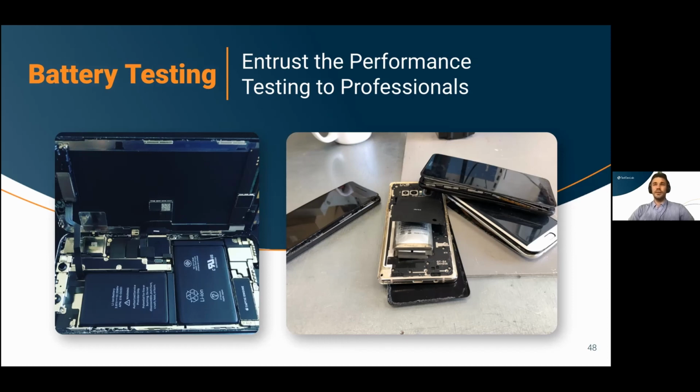Otherwise, we can get to a situation like the one on the right, where in one day, 4 devices were, I would say, blown up. The battery is just expanding because the USB hub was configured improperly. It was working for 2 years. Improper configuration caused all devices to swell in a couple of hours.